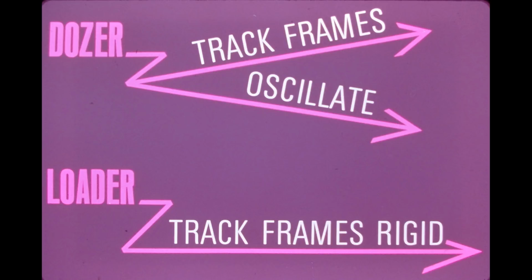The two small dozers in the International line, the TD7C and TD8C, are exceptions in that their undercarriages are rigidly mounted in the same manner as their respective loader counterparts, the 100C and 125C. A rigid undercarriage is used on these small dozers because they will probably never be used in really rough terrain.